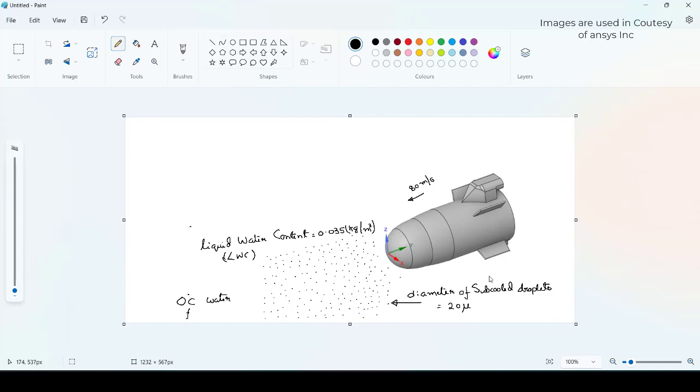The main reason for this is the lack of nucleation. In order to form ice, we need a point or a surface on which nucleation can occur. And these low-diameter droplets cannot easily be converted into ice. That's the reason they are still observed as droplets of subcooled water. It will be like minus 20 or minus 30 degrees centigrade high in the altitude in the clouds, right? So when a helicopter or a missile or anything